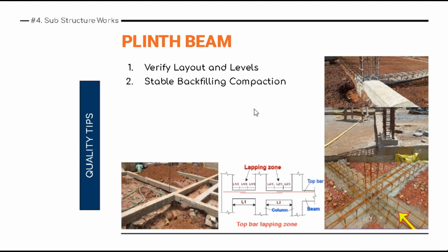Stable backfilling compaction is very important. You can see here a photo or image where the soil compaction or the backfilling is improper, it has gone down, so it gives a very dangerous condition out here. So don't do this. The backfilling compaction should be steady and stable before conducting the plinth beam casting.